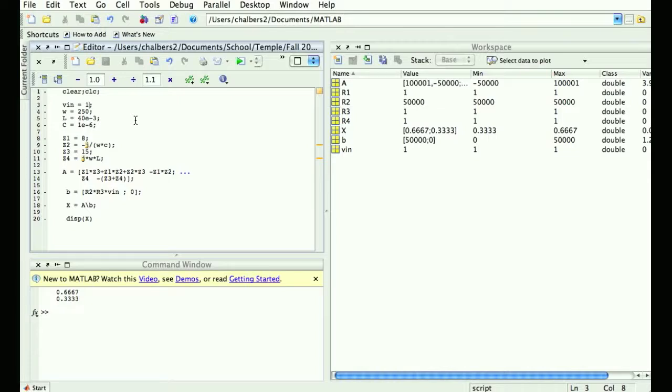Well, there's two ways. One way is I could convert it into rectangular form, which is a bit of a drag. There's another way which works pretty well, which I don't know if you would have learned this, but the shortcut is 60 e to the j times your phase angle. But the phase angle's got to be in radians.